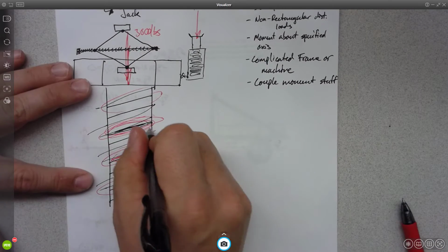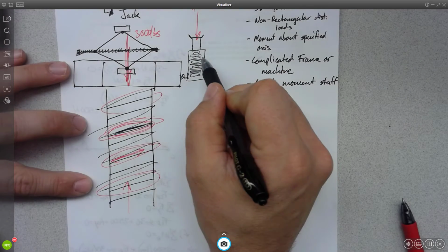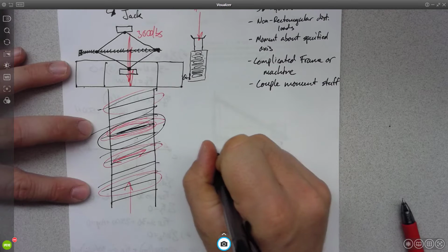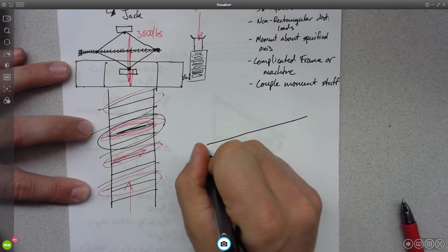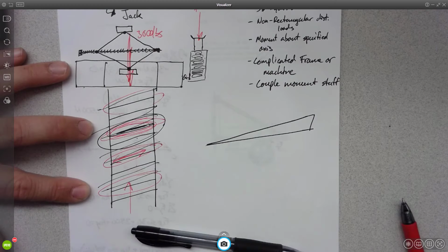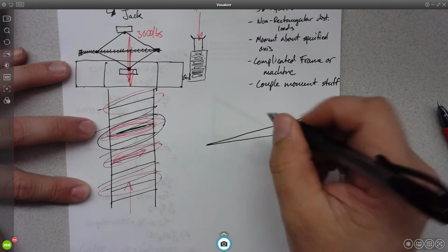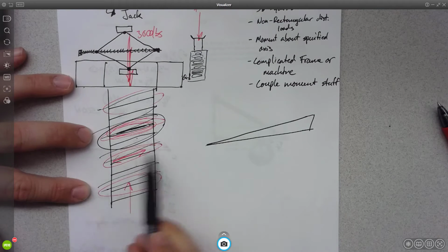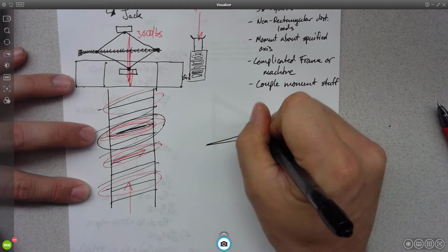And it turns out if we just zoom in, okay, here's a little picture, I zoom in bigger on a bolt. Now I'm going to zoom in just on this, and it looks a whole lot like I've got a wedge or a ramp, right? And then on this ramp, I could treat all of the threads that wrap around this, I could treat them all as a box.